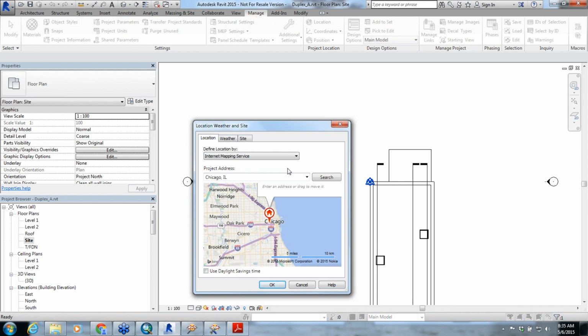However, this is the way the IFC Reader in FME, which the Revit Reader is built on, expects the location to be provided. So what it does is read this site location in lat long, create a custom coordinate system around this location, and assume that the origin point is the 0, 0 of that coordinate system. Yes. Now, in the case of this model, that appears to be what's being done. The survey point and base point are coincident. That's the key thing. If you see the survey point and base point coincident, this is an acceptable method of georeferencing. So that's the default method. Okay.